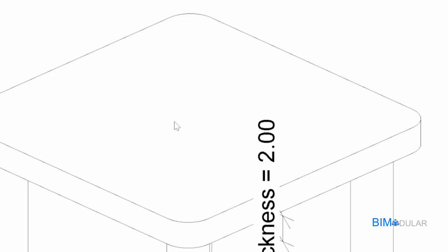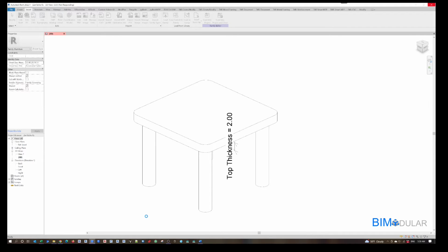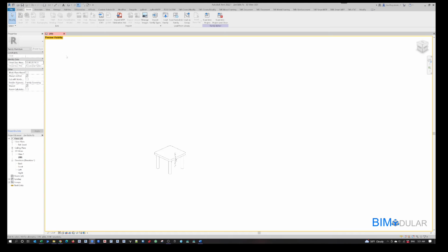We're going to import all the new types, overwrite the existing. And now it's going to load all 20,000 types, hopefully, into the system. As you see, it is taking a little while to load all 20,000 types into the Revit family. We'll also save the family, so you see what happens with the family when you load all types into a family. So definitely this is a very extreme condition. That's done. Go to our preview mode on, zoom back here real quick, and let's look at the 20,000 types that we just loaded in this family.